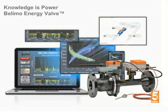Dick, are you hearing some of the same stuff that I've just commented from your customers? Are you hearing some of the same comments from your customers as well? Anyone that I've spoken to that actually has a chilled water system, they all have intimate knowledge of low delta T and what the problems are that are caused by it and the kinds of machinations that they have to get it to actually do to try to contend with it. And if, in fact, they're capacity constrained, they're literally running out of chiller capacity or out of chilled water pump capacity. They literally run out of pumps when they have a severe problem. So it's a problem that's throughout the industry, and this valve does address that.